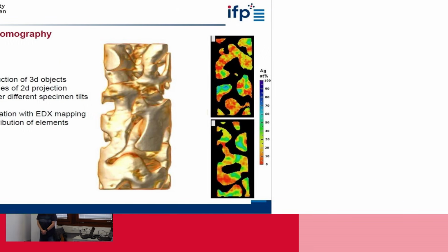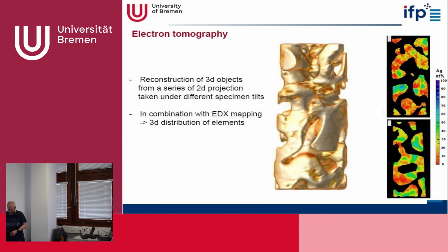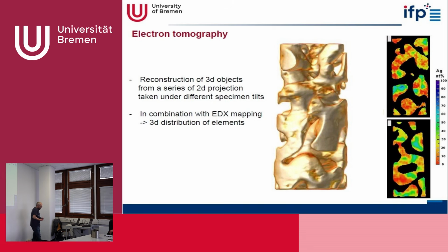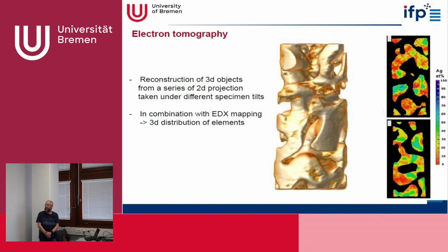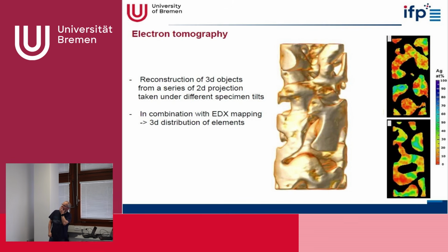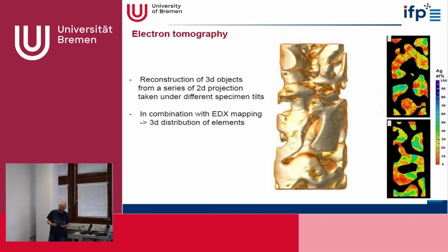Very often samples can be considered as homogeneous in electron beam direction, but this is not always the case. Sometimes people are interested in the 3-dimensional structure of the sample. For example, here this shows a needle-like structure which was cut from a nanoporous gold sample.